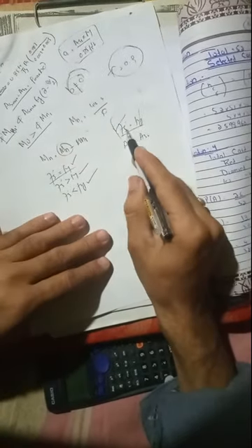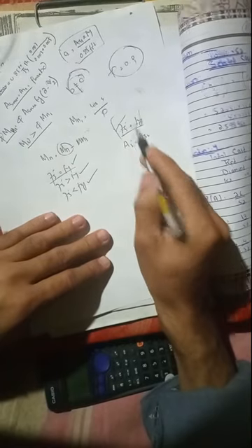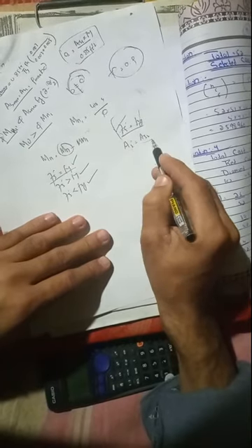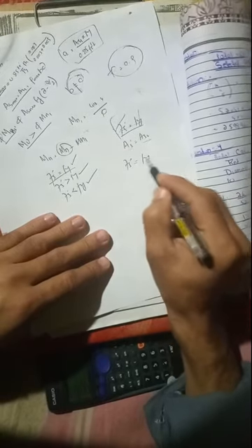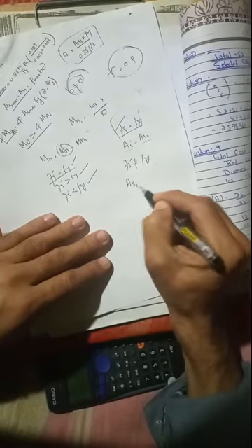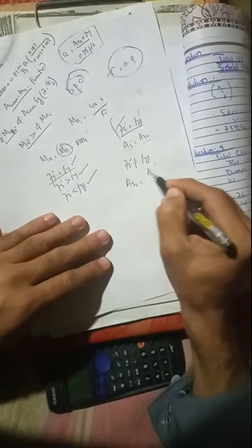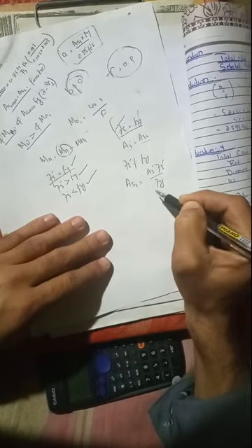Now by using this assumption we can say As prime equals As2. But now as we see fs prime does not equal fy, this means you have to calculate the As2 value from the relationship As prime fs prime divided by fy, right?